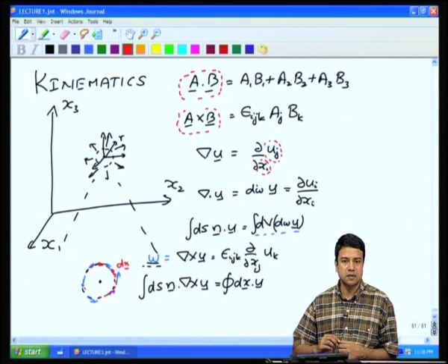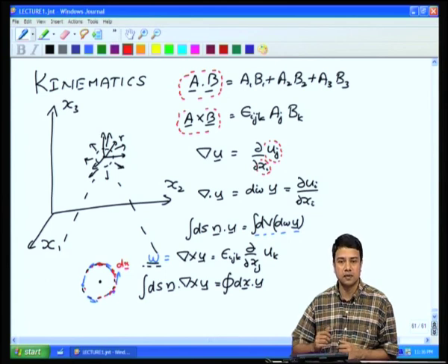Significant simplification results when you have 2-dimensional flows with only 2 components, u1 and u2. In that case, the vector whose curl you take to get the velocity has to be perpendicular to the plane. Okay. So, that we are defined as the stream function vector with direction perpendicular to the plane. So, that basically defines the stream function. Okay. And I had shown you that along lines of constant stream function, the velocity vector is tangent to lines of constant stream function, and the difference in stream function between adjacent lines of constant stream function called streamlines is equal to the net flow through that surface.